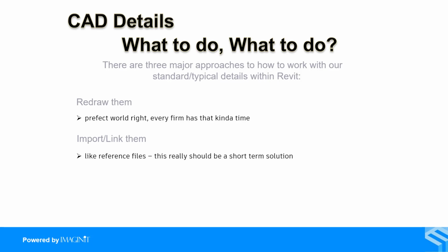You've probably taken that detail and copied it into your project directory, because if it needs to be changed a little bit, tweaked for whatever your application may be, you didn't want to do that to the one in the master library. You want to tweak it for your project specifically, and then you XREF it in. So we would do the same thing.